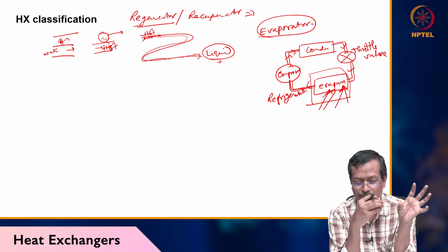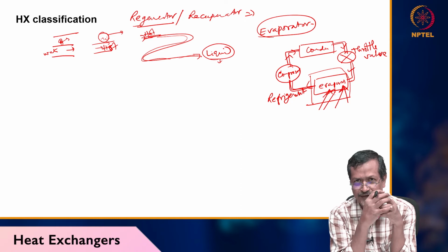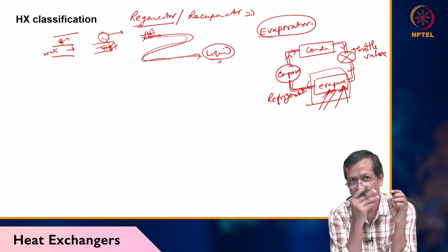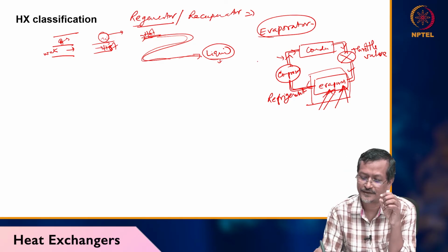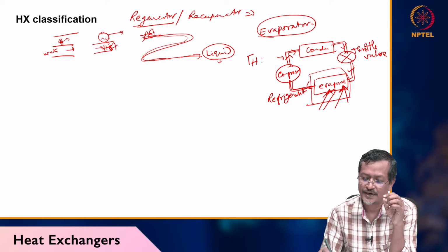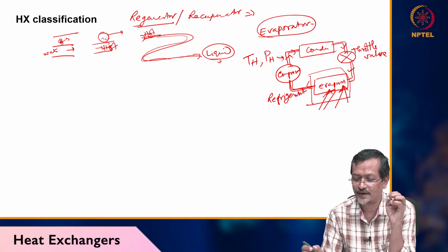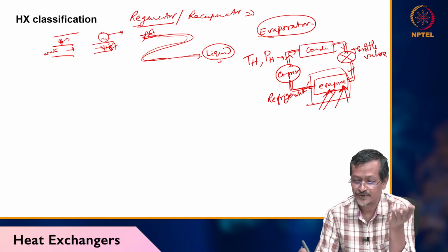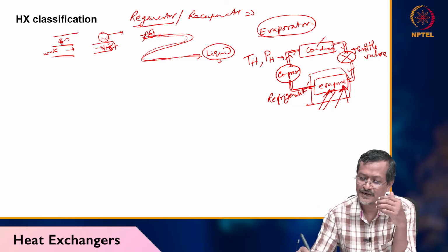So one compressor will be there, and the compressor will compress it again. When it is compressing, again you go to Charles's law. Compression means it will generate lots of heat. So high temperature, high pressure fluid you get after the compressor. That high temperature, high pressure fluid you pass through the condenser, and the condenser will be releasing lots of heat.